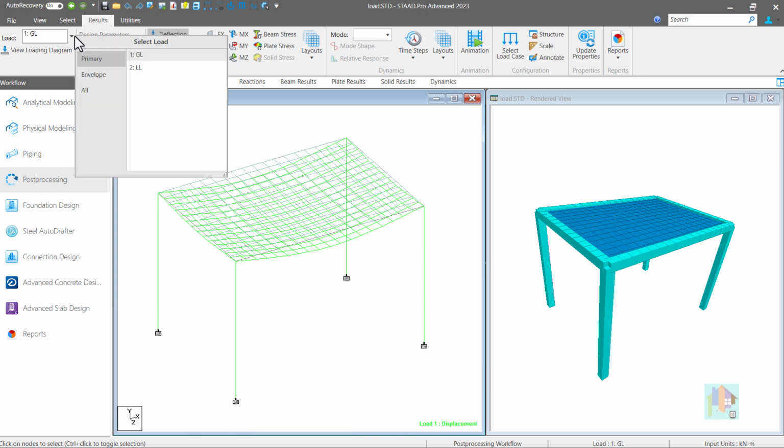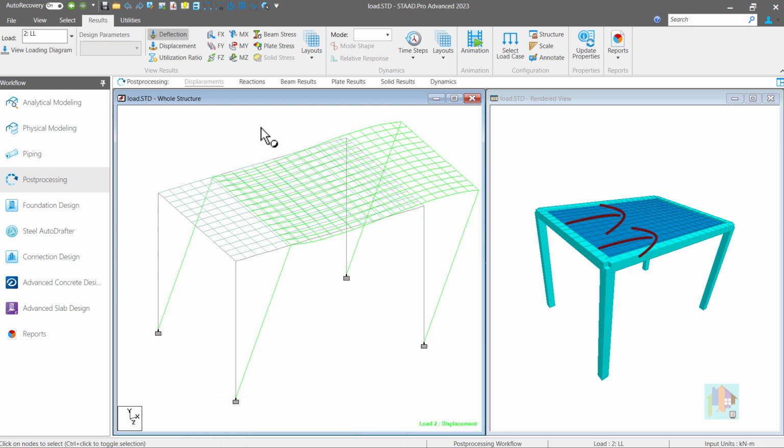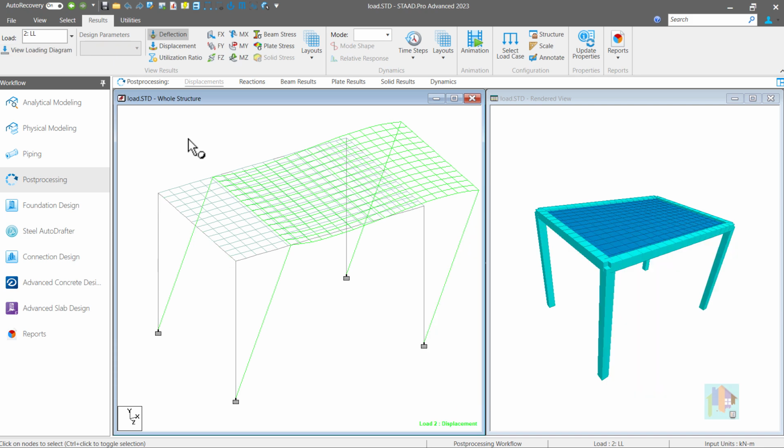When a lateral load is applied on the structure, like a seismic load, floor diaphragm forms a load path and provides significant in-plane stiffness for lateral movement. Concrete slab has higher in-plane moment of inertia. If we don't model or consider this in-plane stiffness during structural analysis, we are not replicating the actual behavior of the structure. Not only that, additional story shear is generated due to torsion at the floor level, which can change the rebar demand of peripheral column. To consider all these effects and proper response of the structure during external load application, it is very important to define the floor slab in the analysis model.